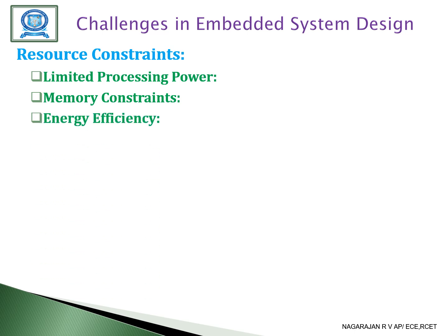The next one is energy efficiency. Many embedded systems operate on battery power, making energy efficiency a primary concern. Power saving techniques include dynamic voltage and frequency scaling, sleep modes, and optimizing code to minimize power hungry operations.